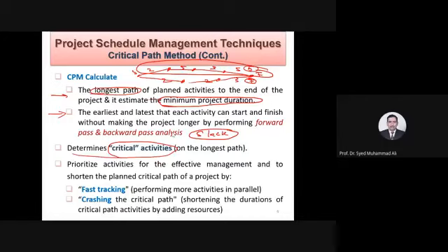Structure means the retaining walls, the drains, and the bridge and causeways are being constructed. The main pavement, the main road section is being constructed, and so on. So there will be multiple activities happening. The activity which has the longest path will be the critical. Any delay on that, even 1 day, your project will be delayed by 1 day.